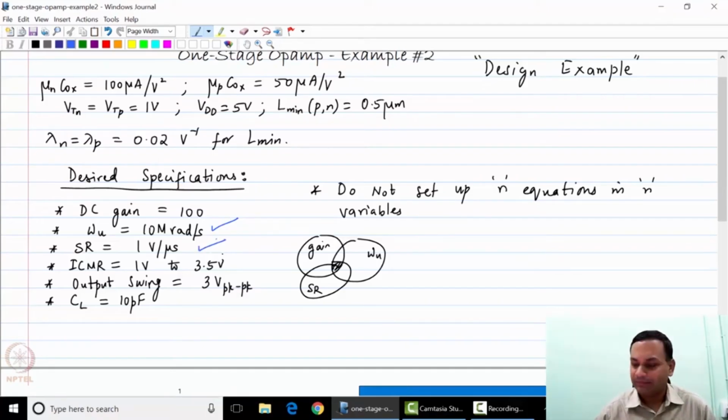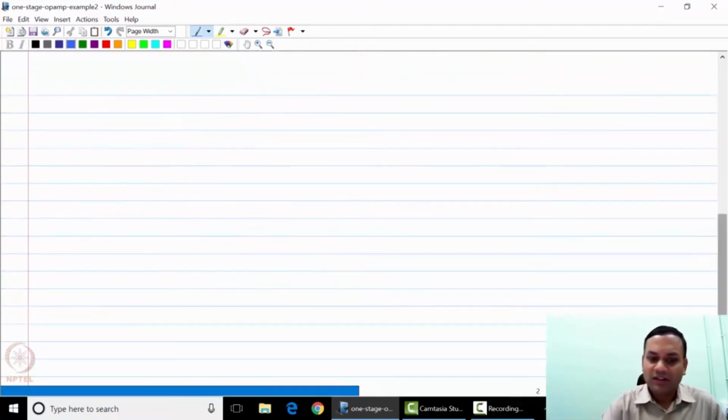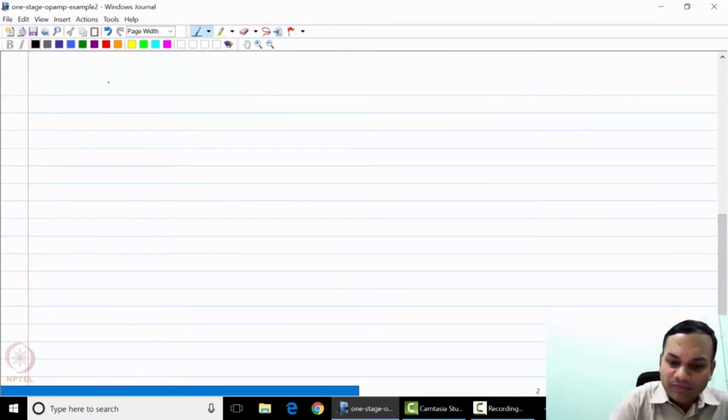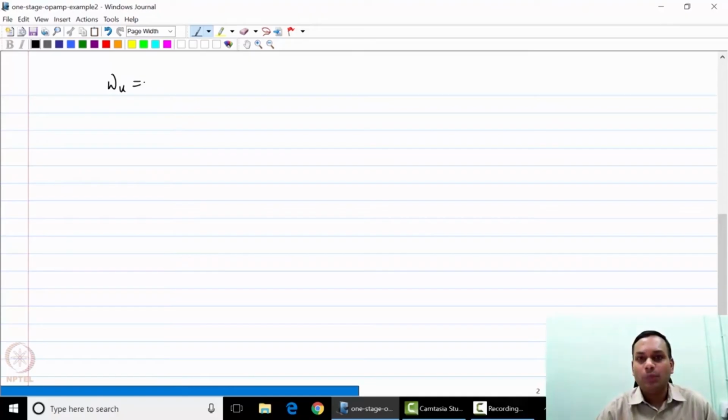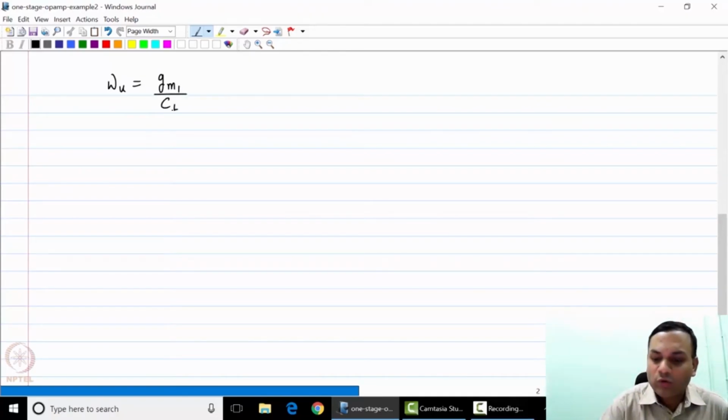So let us start from there. Omega u is nothing but gm1 over CL, where gm1 stands for the transconductance of the input pair.